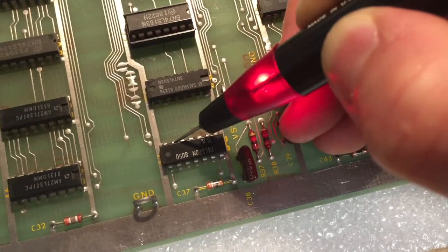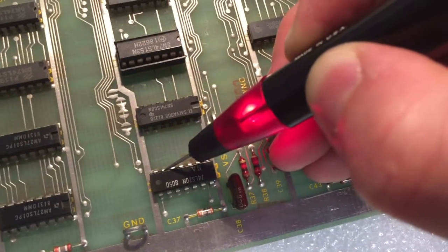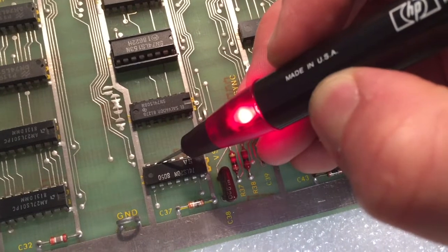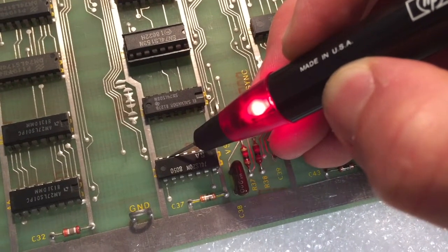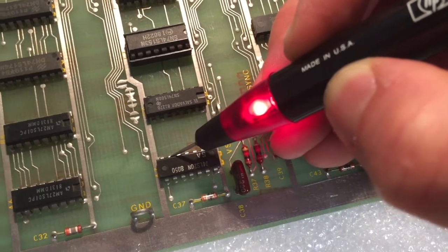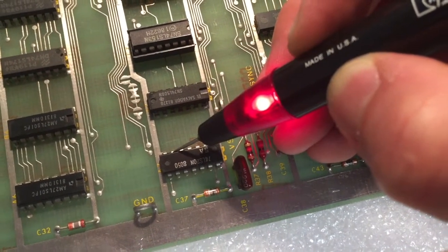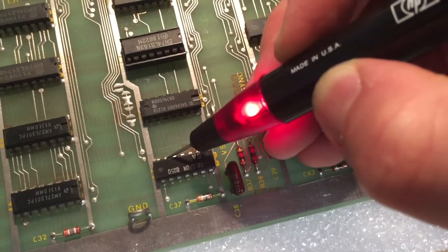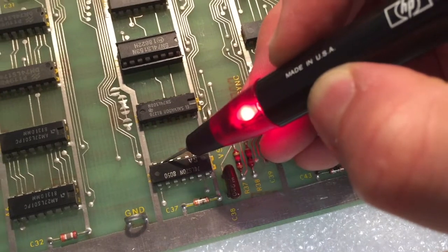This output stays high, and of course this is very suspicious of the logic gate being stuck, because why would you implement a logic gate which outputs a high signal all the time? You could leave it out of the circuit if it would only produce a high output all the time.